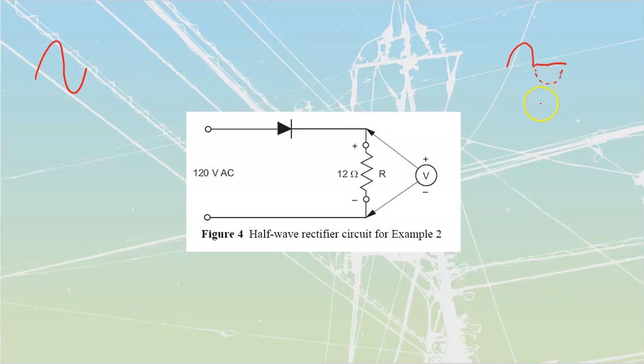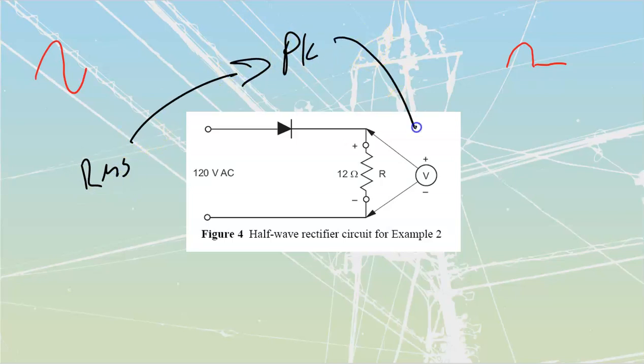We're going to be leaving that at a value of 0 volts for that part of the cycle over there. So that means that if I take a look at it, I'm going to still get normal operation here and then nothing inside of here. This is going to be calculable. We can calculate by doing the same path as what we did before, which is going to be RMS, take it to a peak, take it back down to an RMS, and then calculate our power.